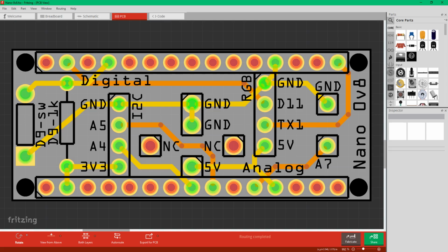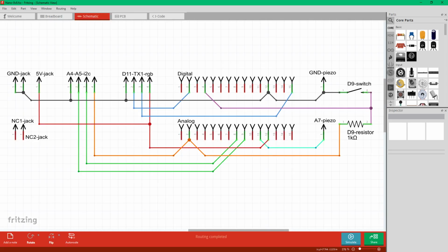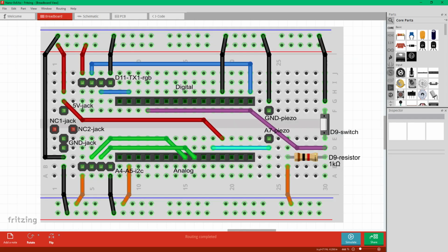If you want to make this PCB, you can find a Fritzing file in the fritzing folder downloaded from GitHub, where you can view the PCB, schematic and breadboard layout. There is also a zip file containing the Gerbers. For an enclosure, I've successfully used a Philips Moire 6-watt light to diffuse the bright LEDs.